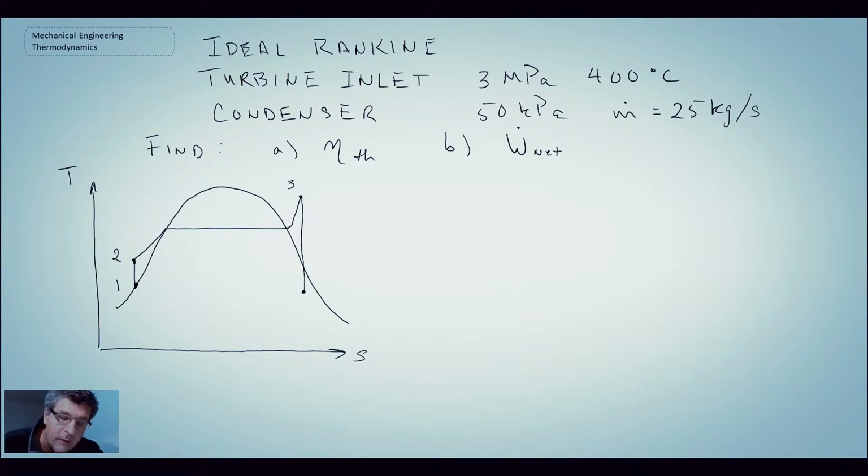Right now, we don't know where we are expanding to. It could be superheated, it could be right on the saturated vapor line, or it could be in the two-phase region. And so that will be state 4, and that takes us back into the condenser.